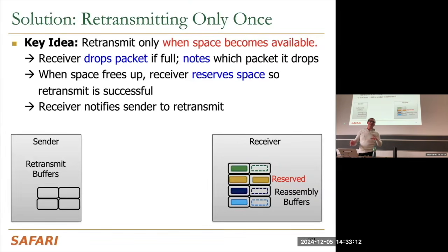Yes, but those are actually small because you're not keeping track of data, right? So that sort of buffering is small. You're really keeping track of some node ID, packet ID, or flit ID. So that's much smaller than a 64-byte or 256-byte cache block, right?